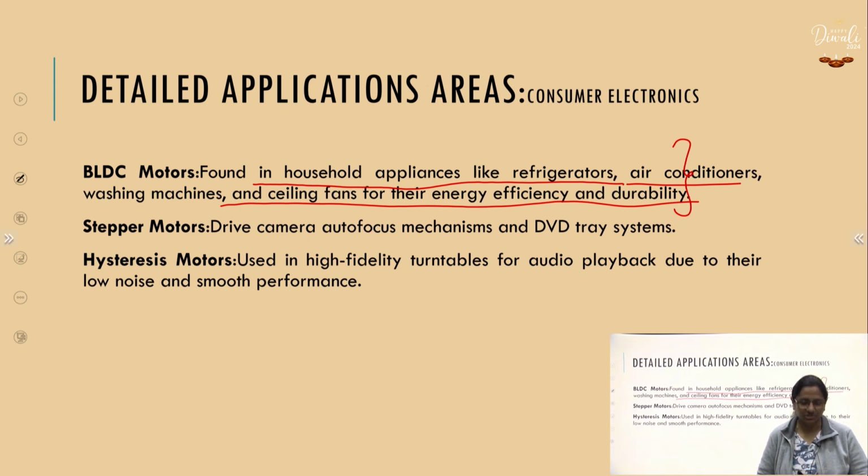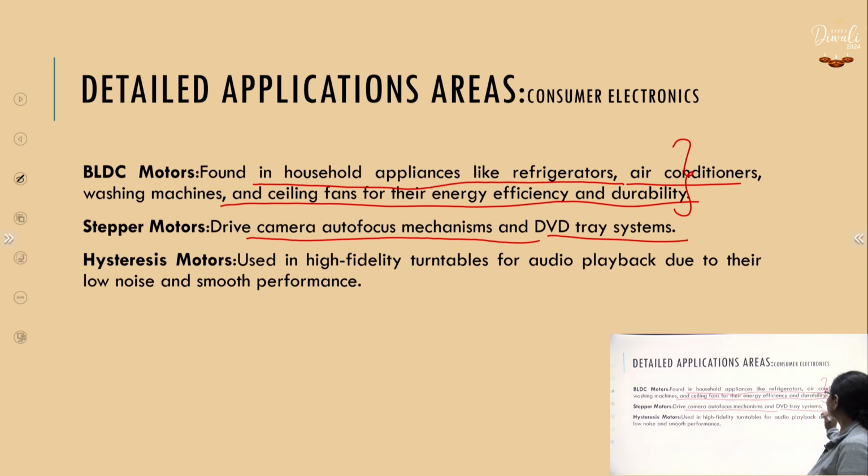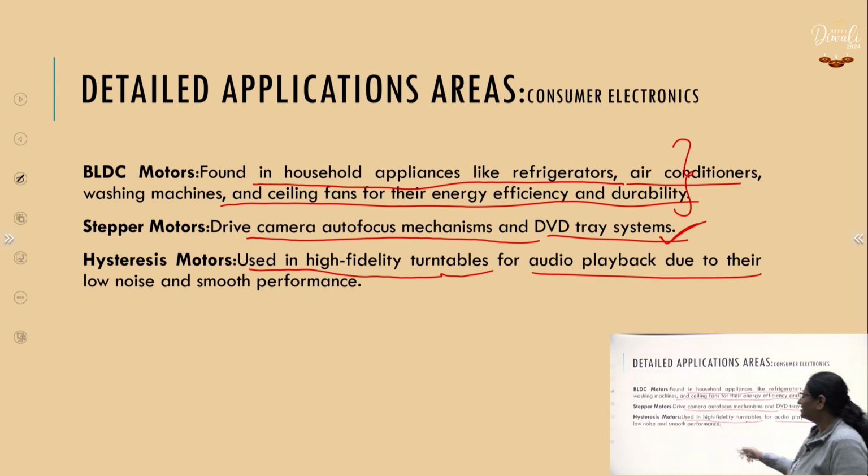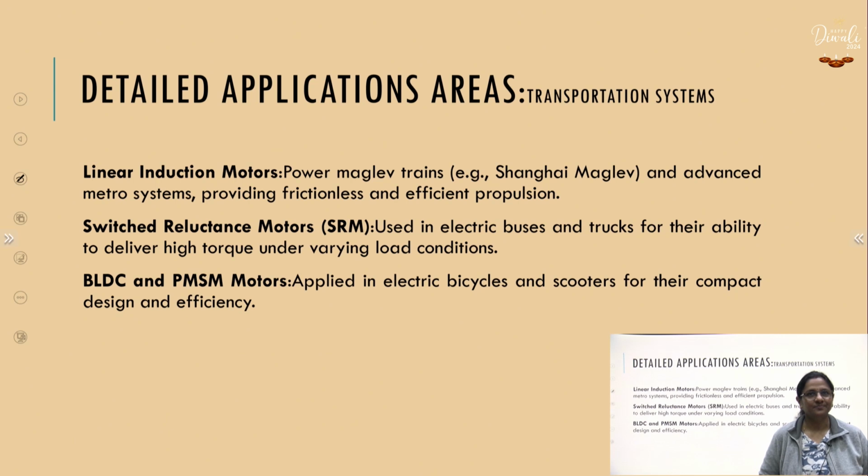In commercial applications, the BLDC motors are replacing the single phase induction motor for better efficiency, compact size with higher power density and efficiency. Then we are having stepper motors. They drive camera autofocus mechanisms and the DVD tray system of the player. Then we are having hysteresis motors. They are used in high fidelity turntables for audio playback due to their low noise and very smooth performance as compared to the other fractional kilowatt motors.